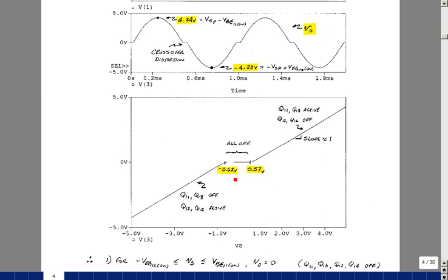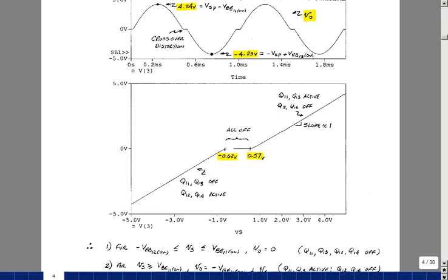So here's the value of voltage of V in before it turns on. The reason these are different is that one's a PNP and one's an NPN transistor on that first stage, with Q11 and Q12. And the same thing with slope 1 over here too. You can also see that, if you look at the individual transistors, when the input is positive, then Q11 and Q13, as we've just shown previously, are on, and when Q12 is off, then there is no chance for base current to go in Q14, so it's also off. And just the opposite happens when we swing negative.